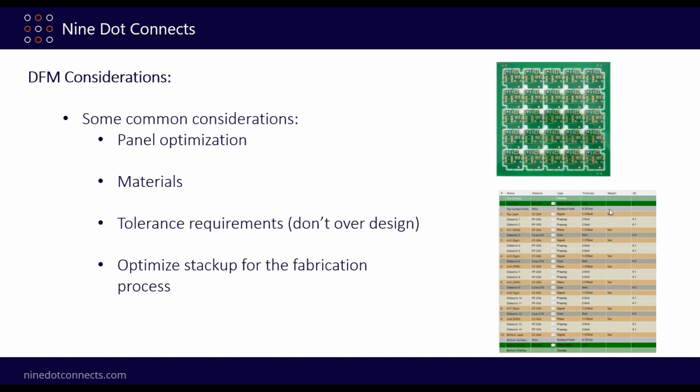And when you start talking about micro vias and buried vias and blind vias, you have to be extremely careful how you set up this stack up. And why add that to your list of things to do when fabricators are very, very happy to do it for you? They don't want complicated designs that they're going to have low yields on, or materials that they can't come up with. They want to help you. So don't forget to use them.